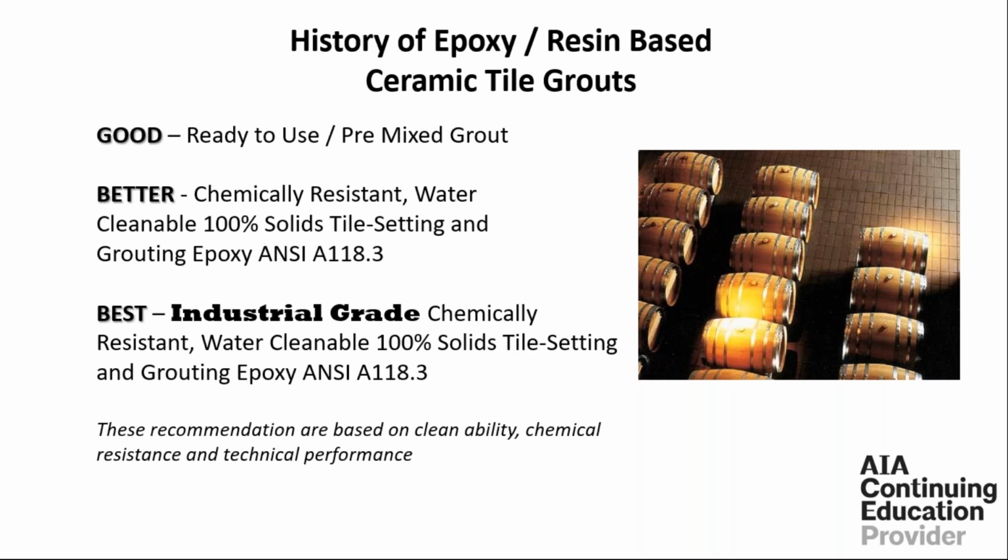epoxy. Your better, of course, is your chemically resistant, water cleanable, 100% solids epoxy, complying with ANSI 118.3. And then your best for your industrial applications is the industrial grade of epoxy. Back of the house, keep this in mind, always use an industrial grade of epoxy. That way you're not going to have a problem a year down the road, 2 years down the road, grout failing on you.